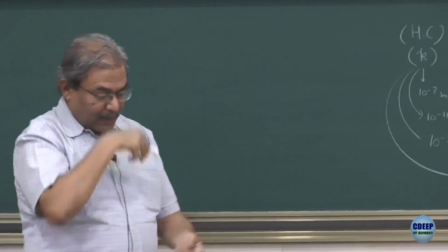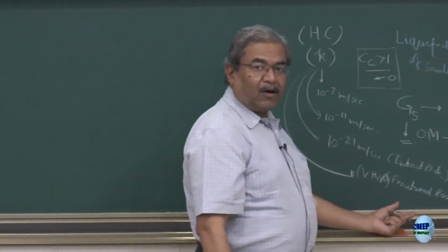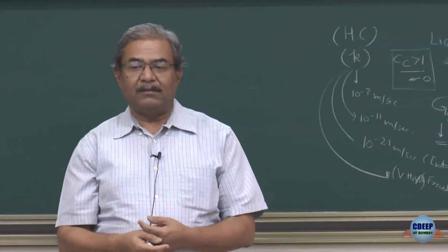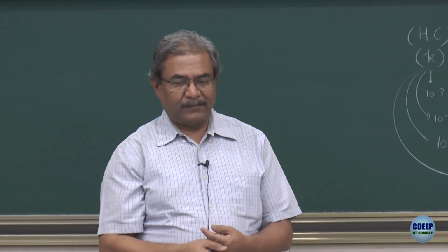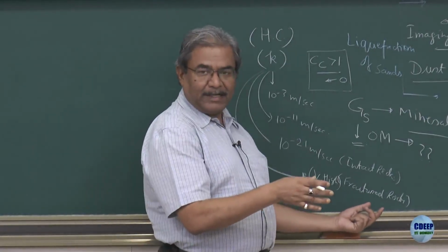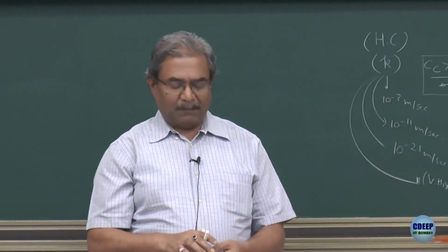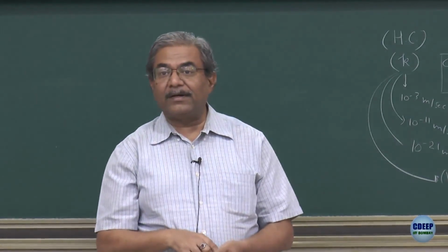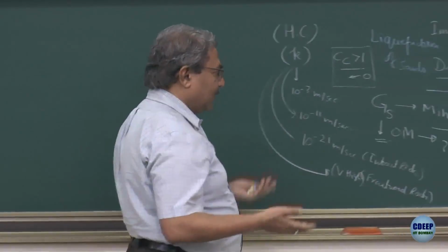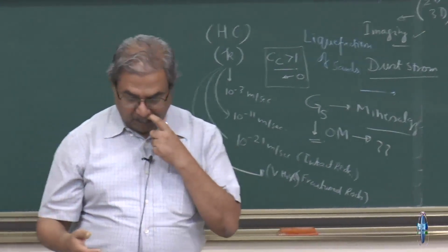So, the question which has been asked in the beginning of the class and we were discussing, when you are dealing with the rocks which are highly fractured, you have to be extremely careful to avoid mishaps. So, the more the discharge of the water inside the cavities is an indication that any time the system might collapse. But it is unfortunate that several tunnels in the country are leaking. So, that is another ignorance or maybe design flaws, you may say.